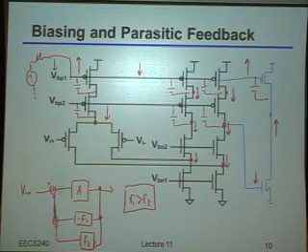cascode here and not there, there'd be some isolation between this node and that node, which would make the negative feedback even smaller. Whereas, in this case, I don't have any isolation between the output and the drain of that PMOS device. The output is the drain of that PMOS. So that would directly couple through CGD, and again, make it much more likely for the positive feedback to actually win. Even if I added a cascode back in here, positive feedback is still likely to win just because you have the extra gain stage.